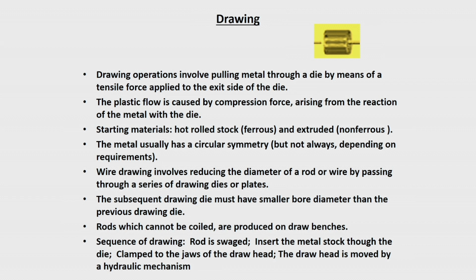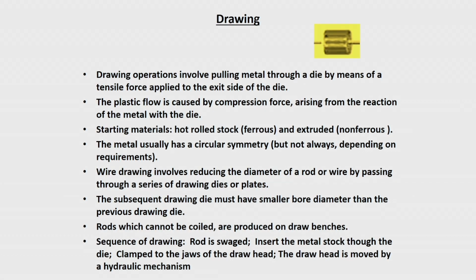Here you are just applying a tensile load, but as I have mentioned earlier in the mechanics of metalworking, though it is a tensile load you are applying, when the workpiece material comes in contact with the die material and exerts a force on it, the nature of the stresses in the deformation zone is compressive. So, you will find the compressive stresses there. The plastic flow is caused by a compression force arising from the reaction of the metal with the die.